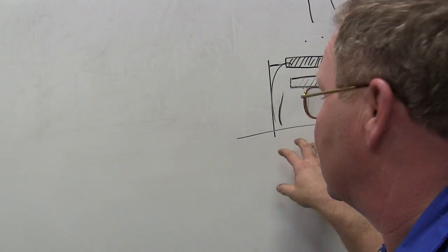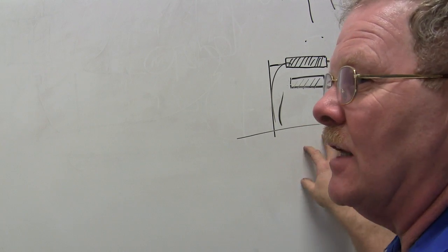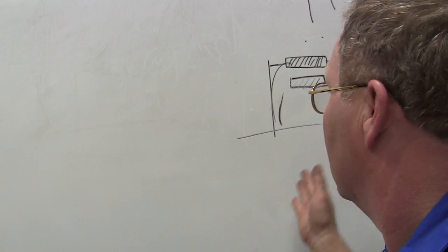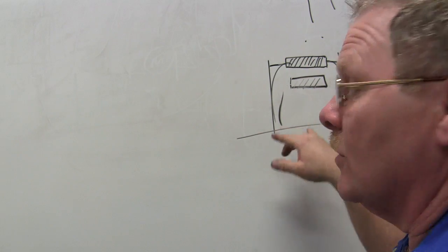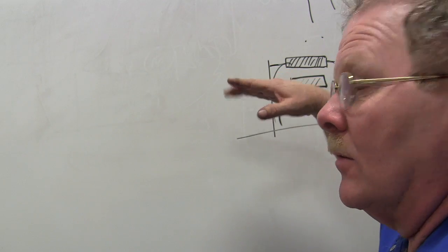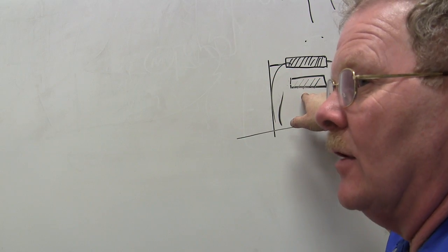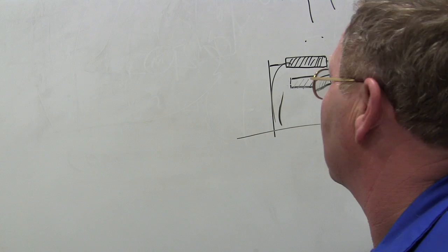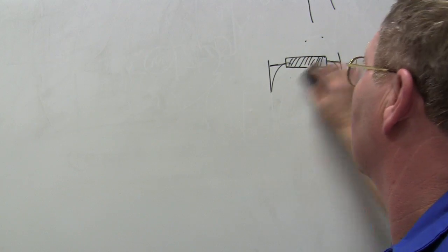Now, it takes the electronics in here and changes that signal to either a frequency signal or a voltage signal, or both. So basically, the voltage is going to be higher whenever it's taking more current to do this, or the frequency will be higher too, see? And they actually interpolate that now as grams per second or pounds per minute or whatever. So that's how those little hot wire sensors work.